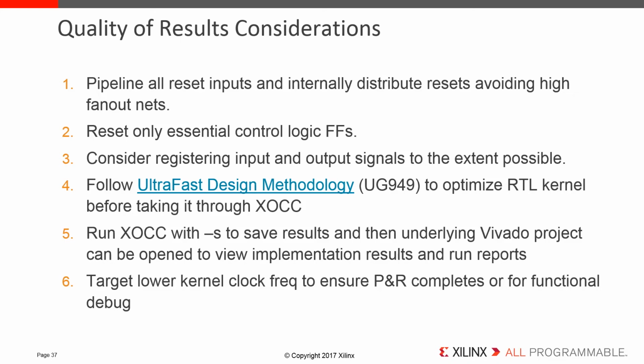The recommendations in the ultra-fast design methodology guide should first be applied at the RTL kernel level before integrating the design at the system compile level. Another tip is that XOCC can be run with the -S option to save temp files, allowing you to open the Vivado project standalone. And always aim for functional correctness of the design first by lowering the target clock frequency before optimizing the design for the target clock frequency.